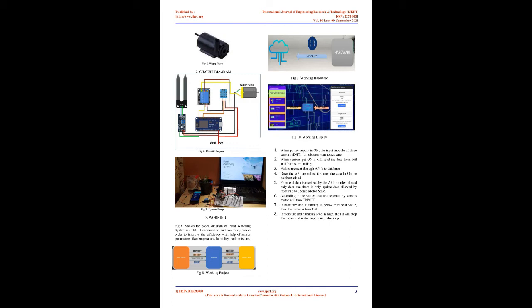A thermistor changes its resistance with change of temperature because it is a variable resistor. These sensors are made by sintering of semiconductive materials, ceramic and polymers, which provide large changes in resistance with just small changes in temperature. The term NTC means negative temperature coefficient, which means that the resistance decreases with increase of the temperature.